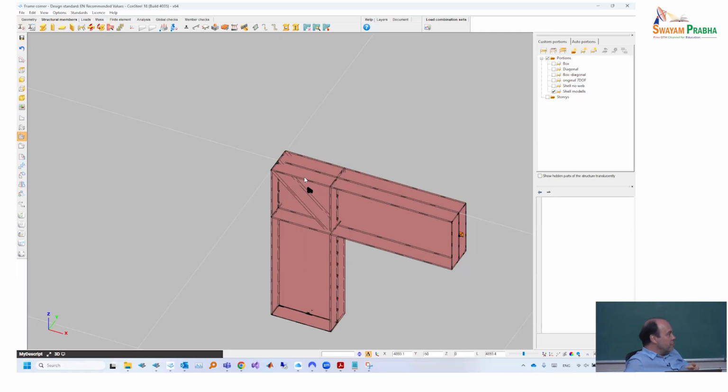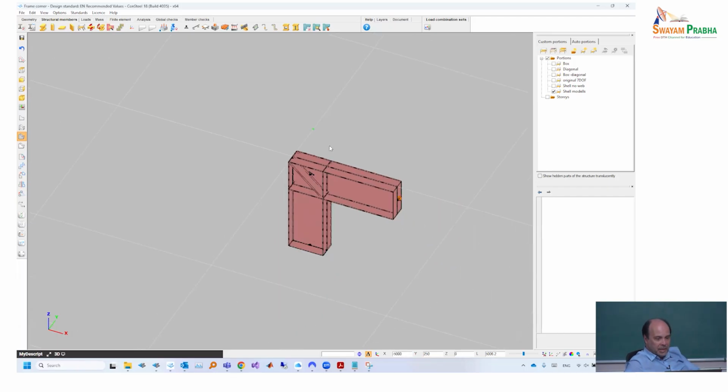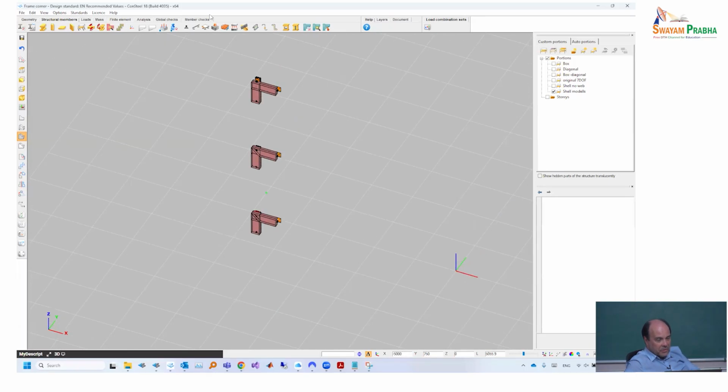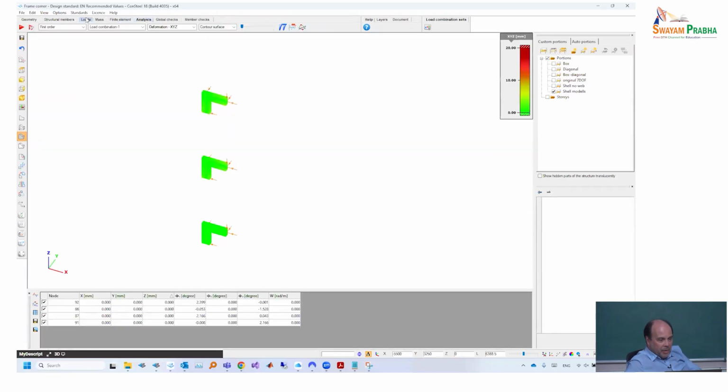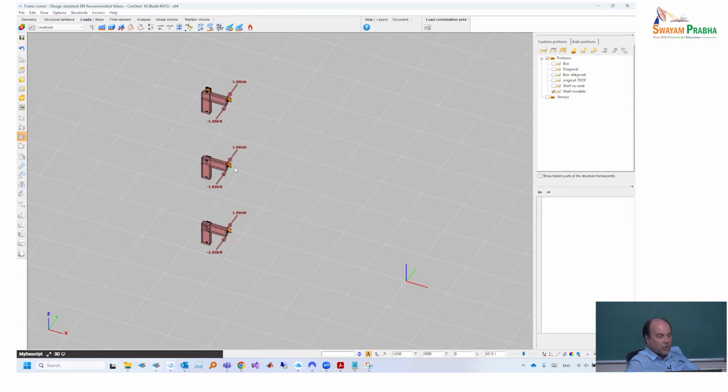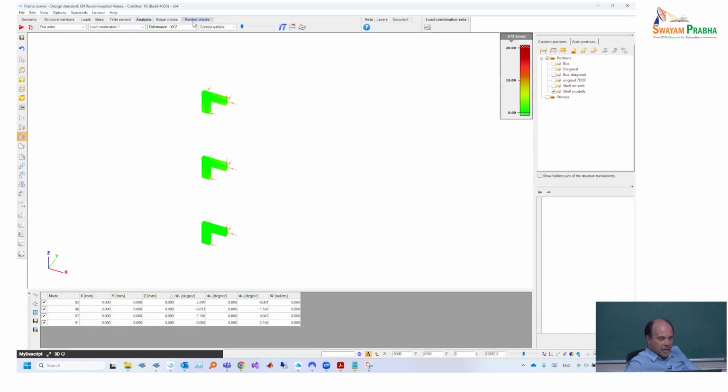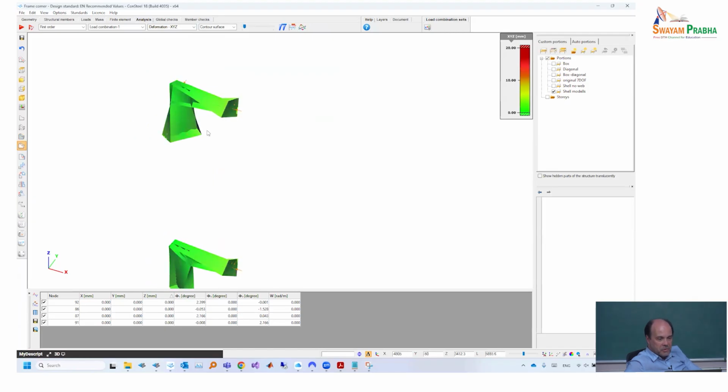And I'm not very sure that engineers are really aware of whether it has any impact. I think very often people believe that they put this diagonal only to prevent the buckling of the shear panel and not assigning any other meaning to that. But actually it's very interesting that this is not only about that. I applied on each of them a torque, so a pair of horizontal forces on the beam, and with shell elements I made a calculation to see how they behave. And actually it's very interesting.